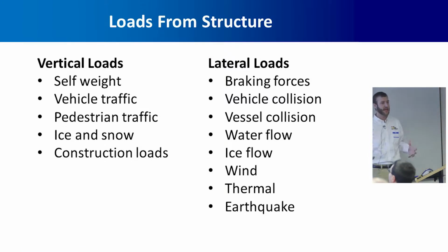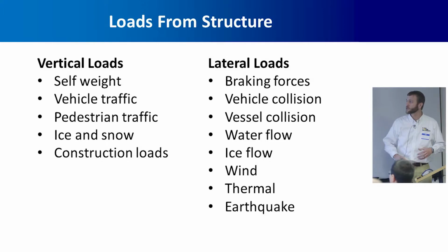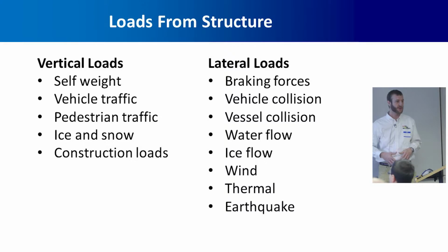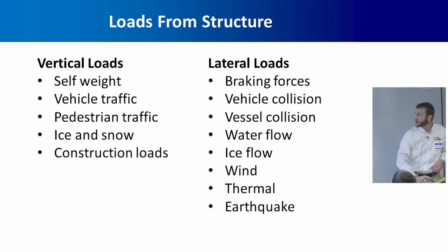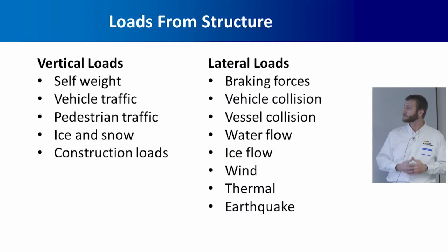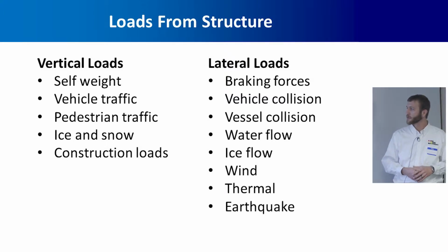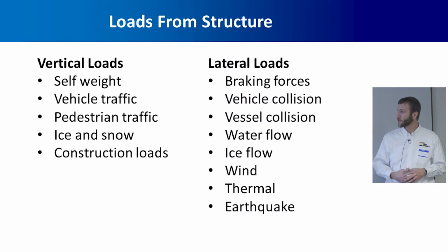Any foundation's basic function is to resist the loads from the structure. Those loads can either be vertical loads, which are pretty much weights from the structure or weights from stuff on the structure, and then lateral loads, which are basically forces acting on the structure, like wind or water or earthquake loads.